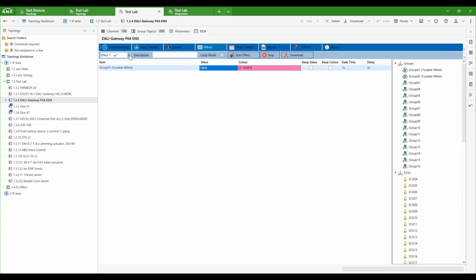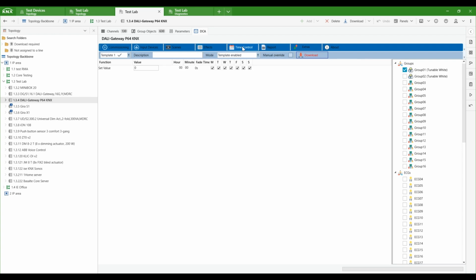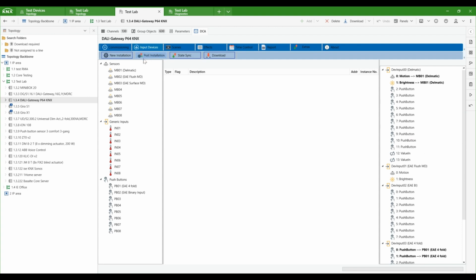It might be a number of effects, and what also is really handy with these tools is once you've got an effect, or you've got a schedule for your human-centric lighting, you can always import and export. Okay, so that will go back into an XML file, and then you can import it for the next time you're doing it as well. And same with this, it has got true color timer on it, so you can run a certain time control thing with it as well.